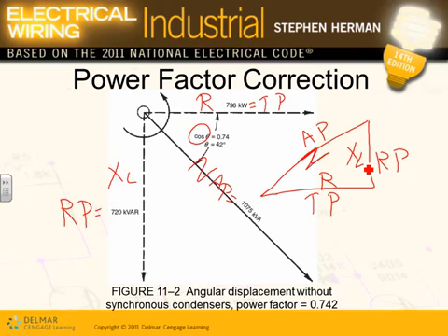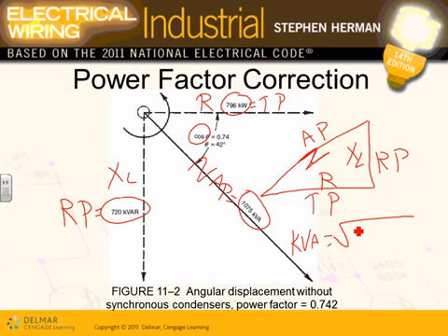In this example, guys, they're giving you data. Here's the volt-amps, here's the watts, and here's the kVAR. And the relationship between these, if you remember: kVA equals, by the Pythagorean theorem, the square root of kW squared plus kVAR squared. You square them to find the apparent power. So if they give you the kW and the kVAR, that will get you the apparent power. Any comments, guys? Any questions?